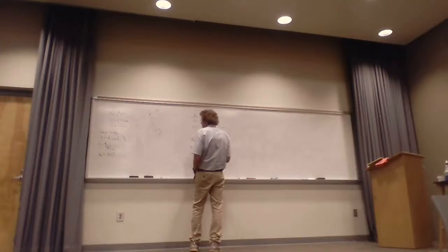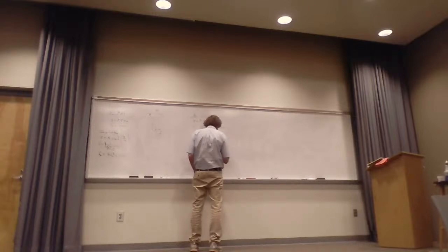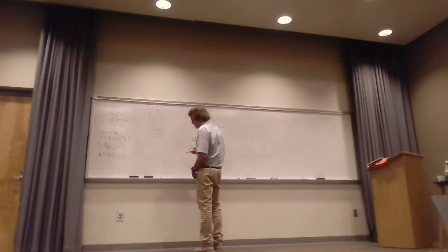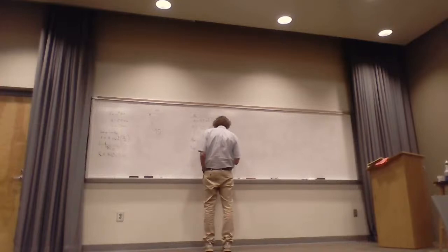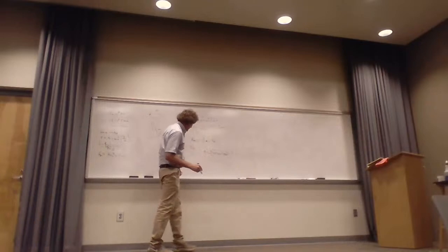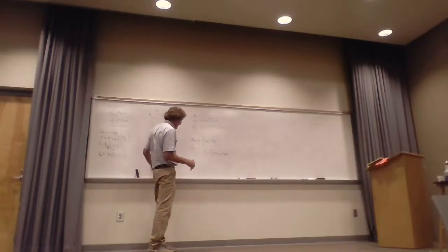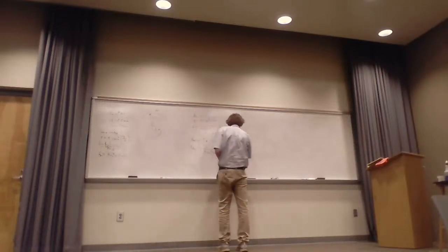This would be for the gold. It's half a millimeter, or 5 times 10 to the minus 4th meters. So 2 pi a times the skin depth, which for gold was 8 microns, or 8 times 10 to the minus 6. When you do that, you're going to get the AC resistance of the gold. I'm going to leave it right there.